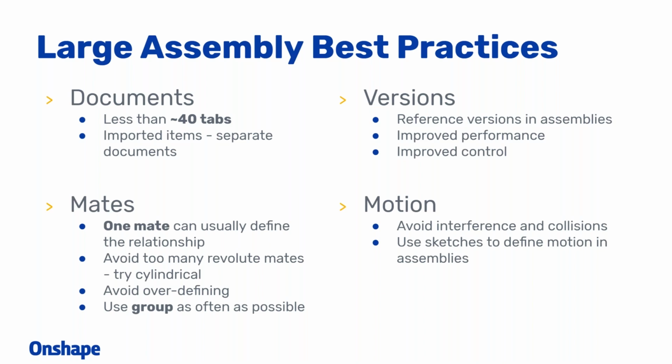And another best practice is you want to avoid interferences and collisions in regards to motion. Whenever you have parts in an assembly that end up overlapping or interfering, this leads to some problems within any sort of CAD package. Not only does it not make sense to a judge when they're looking at your assembly, it also doesn't really make sense to the background solvers in these packages.